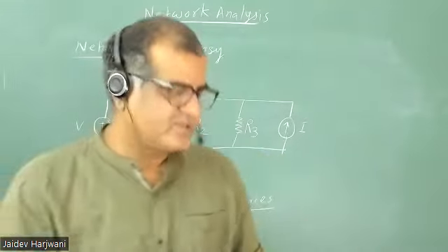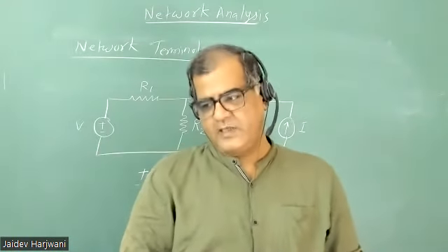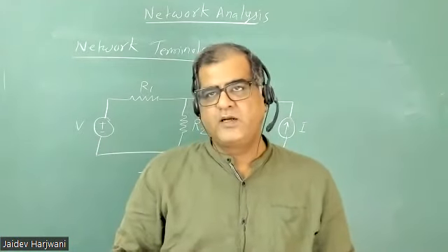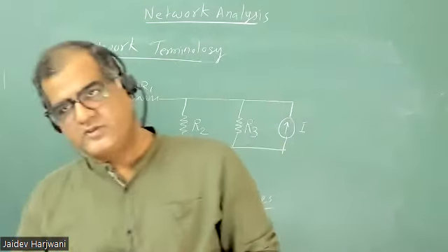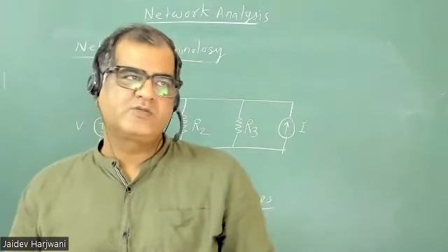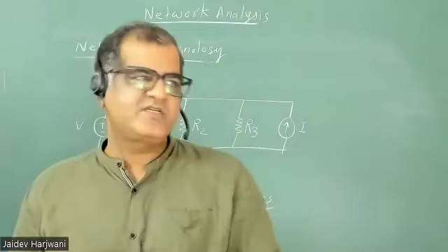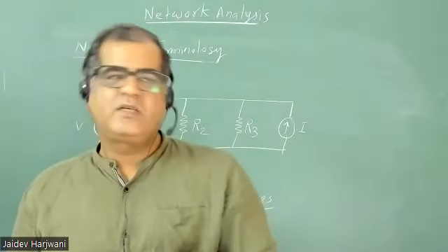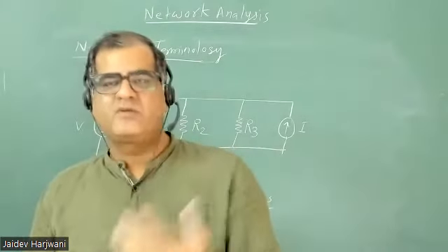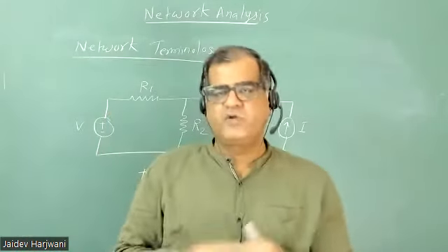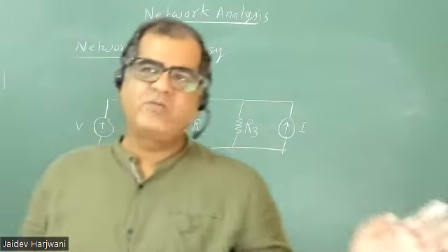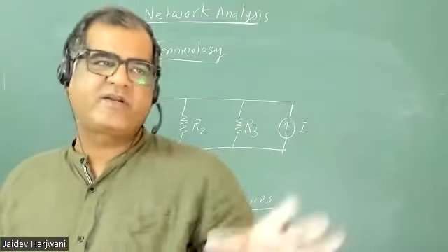And there are some sources which are called dependent sources, which we are not going to deal with right now in this chapter. For a dependent voltage source, the voltage difference across the source depends on the circuit condition. Similarly, how much current is passing through that element depends on the circuit conditions. Dependent sources are basically used in modeling, for example an operational amplifier or a transistor.